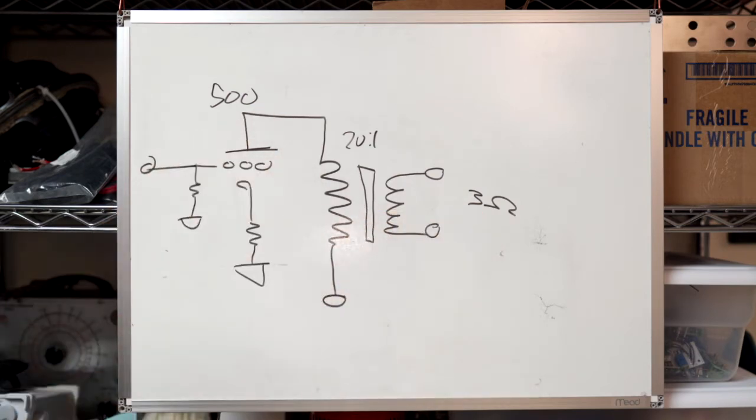the tube amplifiers are sort of the opposite of solid state amplifiers in this other way as well, in that they're basically okay driving a short. Now you don't want to do it all the time or push maximum power into a shorted output. You're going to cause problems there, but they're perfectly happy to drive low power into a dead short for a short period of time without damaging anything.